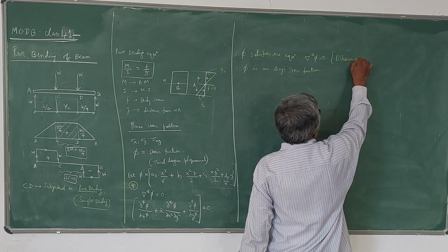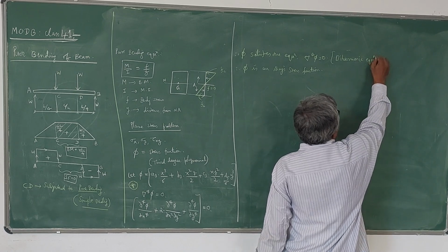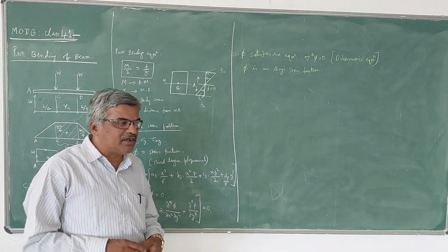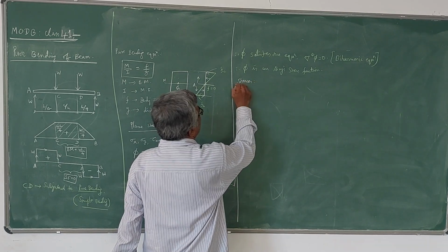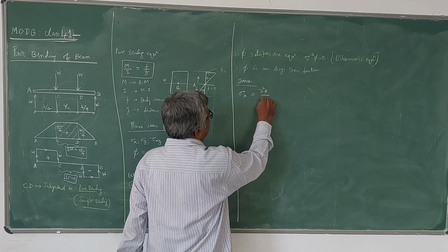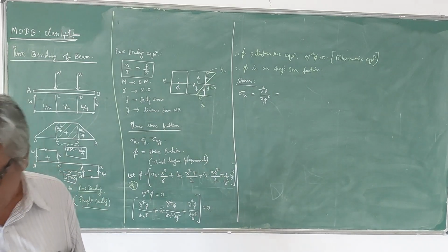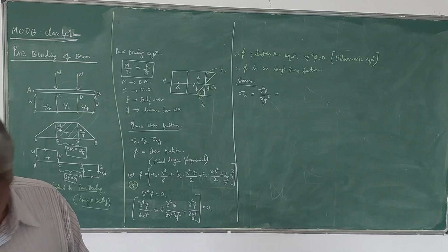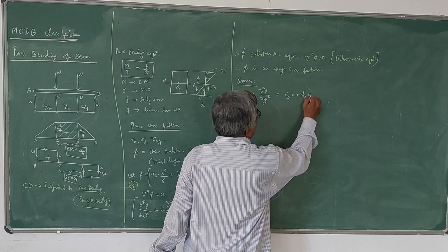Harmonic equation means del square phi is equal to 0. Biharmonic means del power 4 is equal to 0. So phi is an Airy stress function, and once it is, you can get the stresses like this. Stress sigma x is defined as dou square phi by dou y square. If you differentiate phi twice with respect to y, you get c3 x plus d3 y.